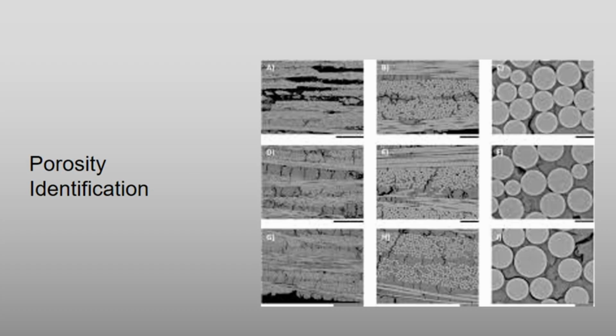Separation and repeating. Porosity identification. Because the polymer shrinks by up to 30% during pyrolysis, the part develops microscopic cracks and voids. It involves mapping distinct defect categories to evaluate matrix densification efficiency. This demonstrates how pore networks form across various fiber layouts, material boundaries, and structural matrices.